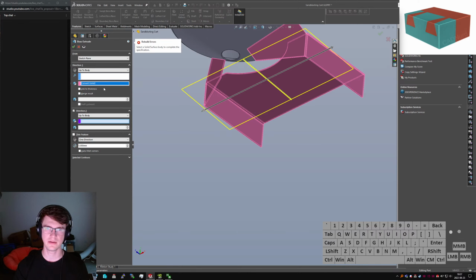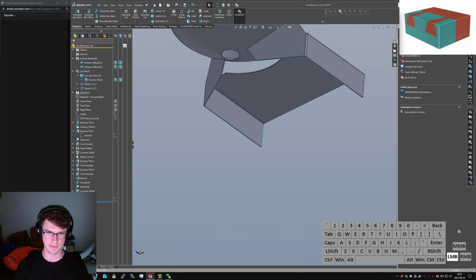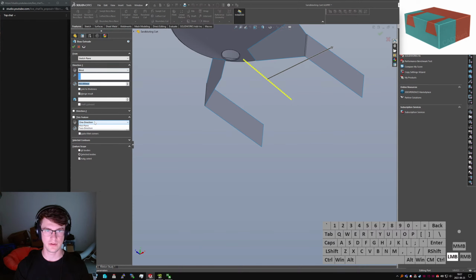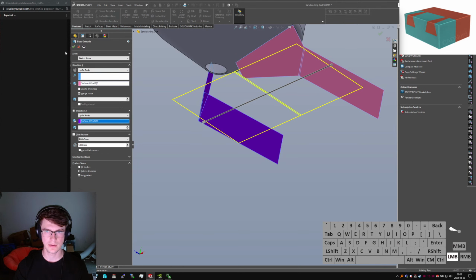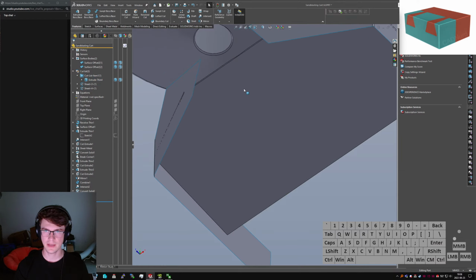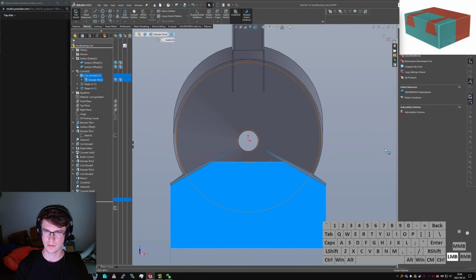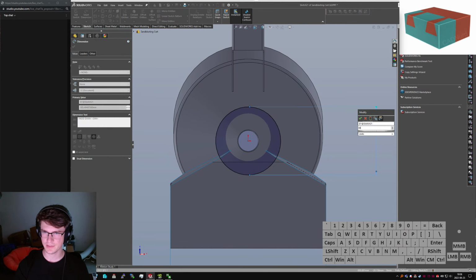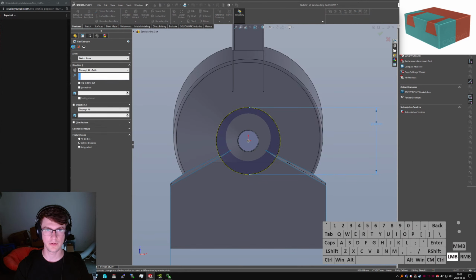Oh, solid surface body, that's rude. Okay, so in that case, we can just come down here after the surface offset, hide that, and when I go about it, make that mid-plane even so that's nice and careful. Up to body, up to body. There we go. So now I can do an extruded cut as well. Make sure that we're well clear of the center there, say 300 maybe. Extruded cut. Through all both. Sounds good.